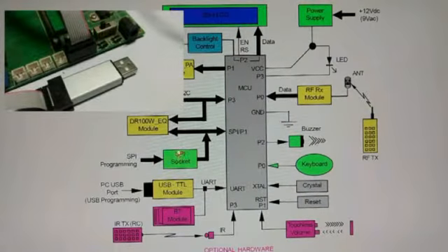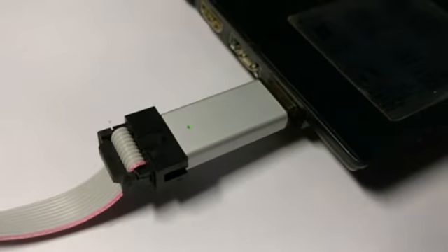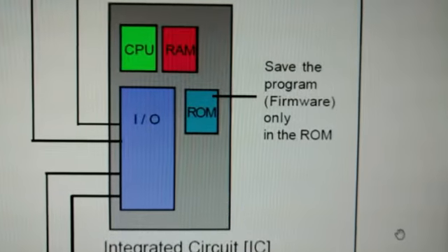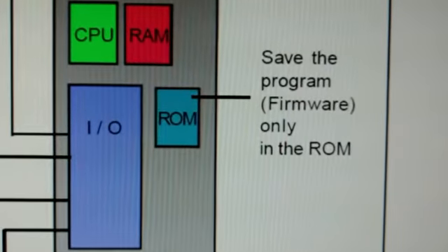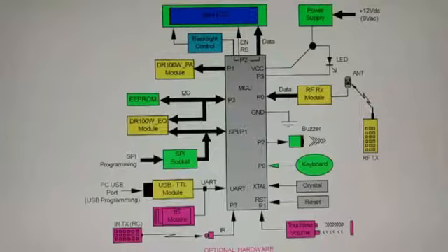and then we have flash programmable application software in the computer, and we send the hex code and burn it into the ROM of the MCU. So that is the way we program the Atmel 8051 core MCU by means of SPI communication.